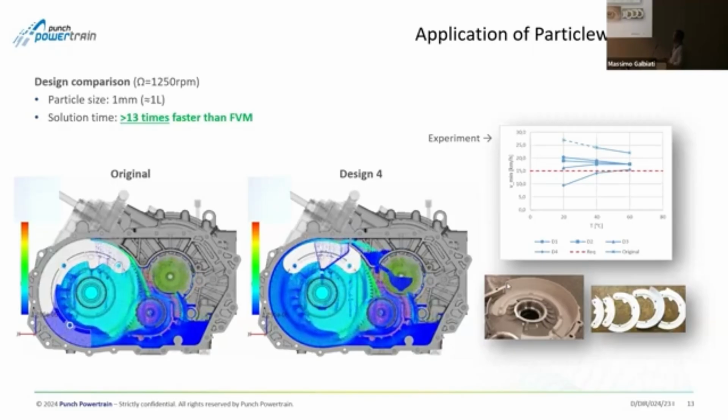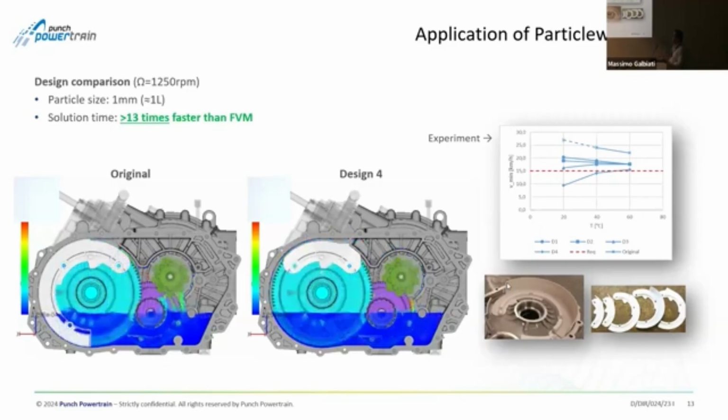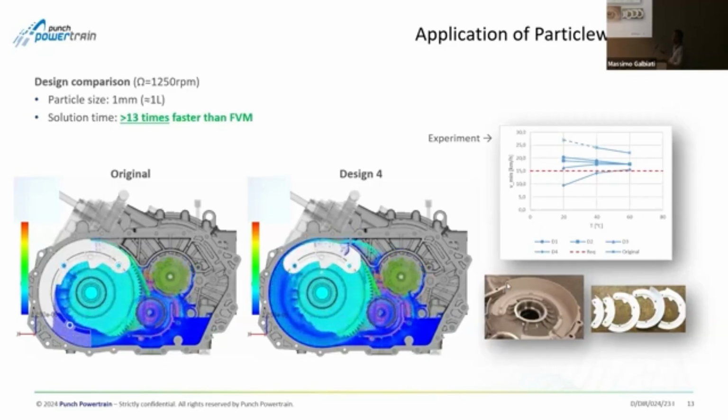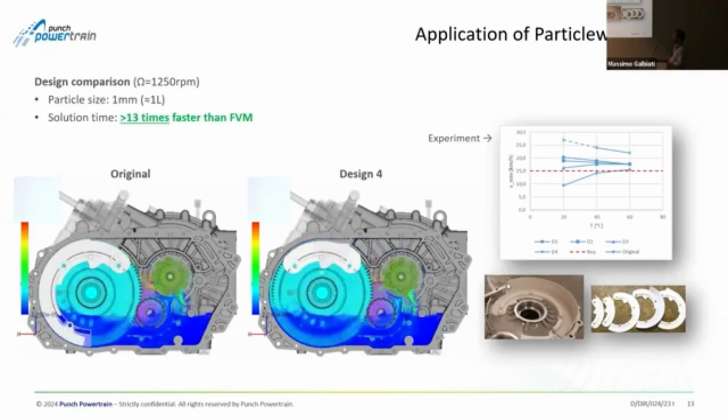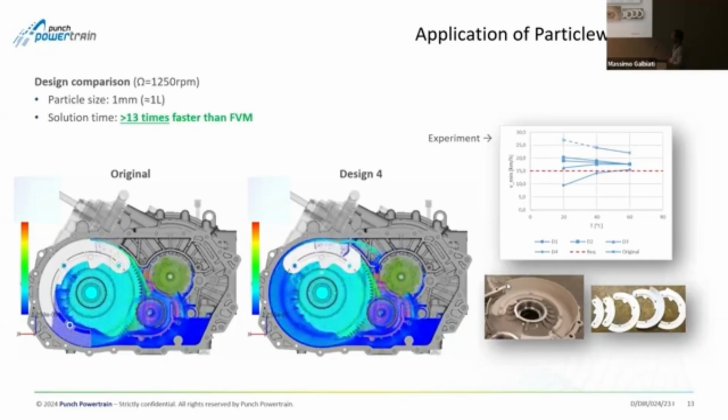For a specific reason, in this case, for example, the feeding with oil of the rotor cooling system. In the Z axis we have a hole which goes through the rotor and cools down the bearings. This approach is already investigated by many electromobility companies in the business.